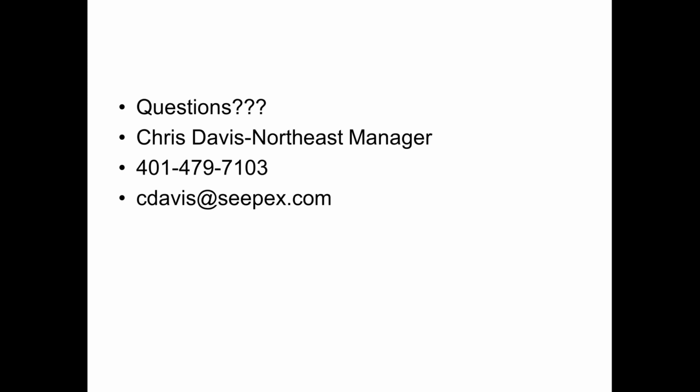And so if they had an application, they just need to get the details to us or to you, and then you would take over from picking a material standpoint, Chris. Correct. There's a lot of different things that we would ask as far as initial questions, but mainly if we knew exactly the type of media that we needed to move percentage-wise, it would just be about finding the right elastomer and metal choice. As long as there's elastomer available and a metal, and we can compress it to make a rotor and stator, we're in good shape.